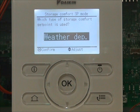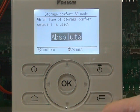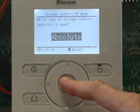The reason we have a weather dependent hot water set point is in winter the mains water comes in a lot colder, could come in as low as 4 degrees. In that case we will be diluting our domestic hot water in our hot water tank, so to overcome that we can heat our hot water to a higher temperature. Normally people set it to absolute so that we've got a fixed set point temperature in our hot water tank all year round. We click on OK.